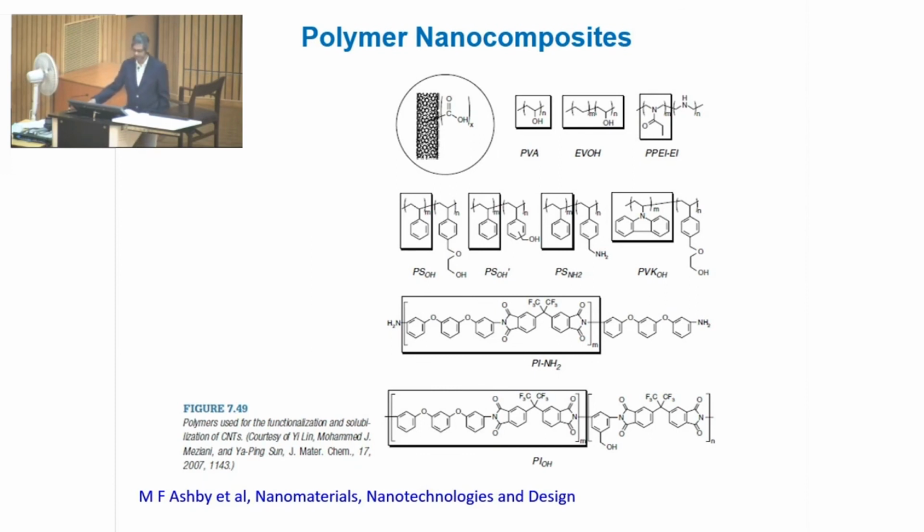The major reason for the discrepancy is the large thermal resistance that exists between the polymer matrix and the CNT surface. Because CNT possesses a high surface to volume ratio, when CNT is dispersed in a polymer matrix, a large interfacial area creates a significant resistance, and this effect has been attributed to the difference in the phonon dispersion or phonon frequency between the CNT and the polymer matrix.